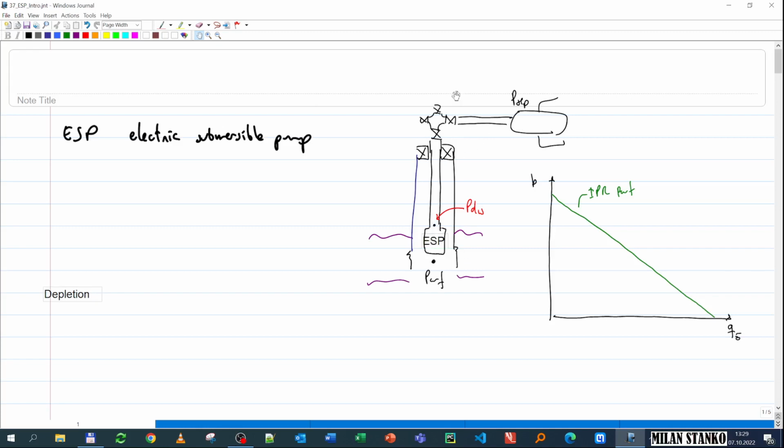And then I'm going to plot also the required pressure curve, which is the pressure that I require to flow against separator pressure for different rates and when flowing exactly at the discharge of the pump. So that curve looks like that. Okay, this is my TPR, and this is for a constant wellhead pressure. So if I assume that I put these two systems together with no pump, then the rate that this well will produce will be this one, Q oil star.